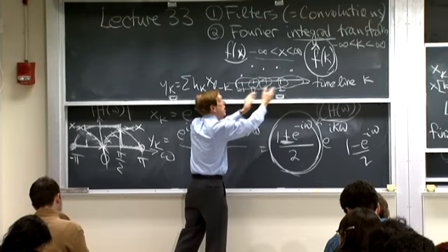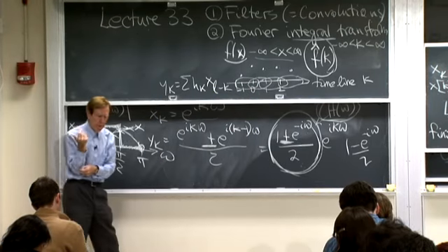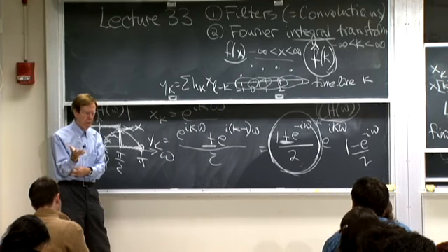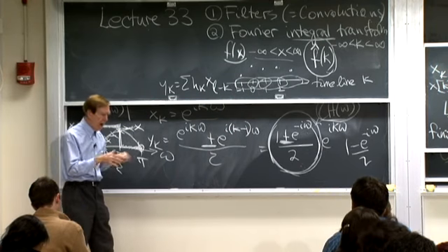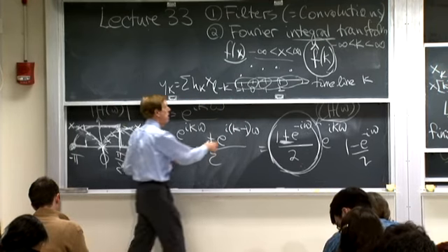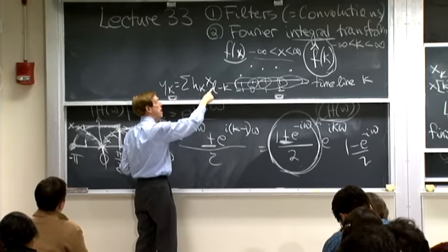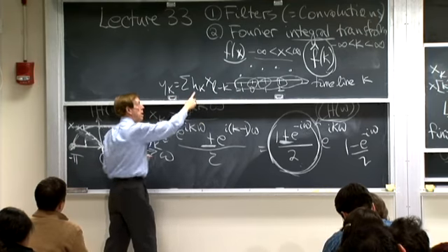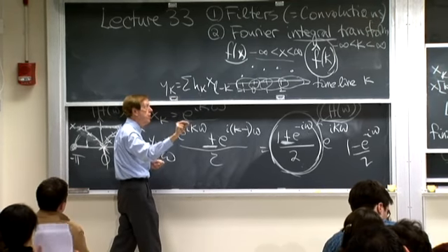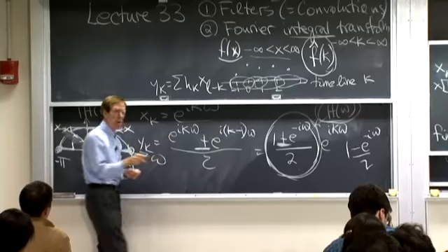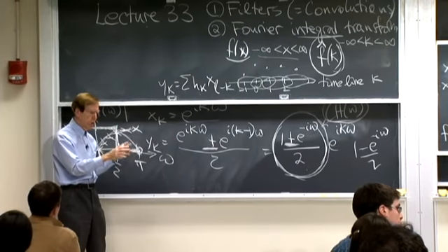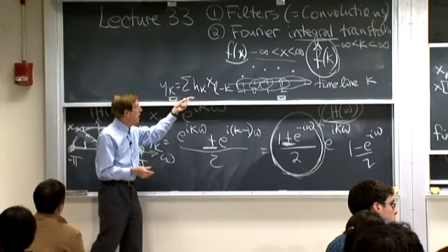And then you just move it along, so it needs a delay. That's about the content of a filter: multipliers that will multiply by the h's. So in come the x's, multiply by the h's, do the addition, and do a shift to get on to the next one.